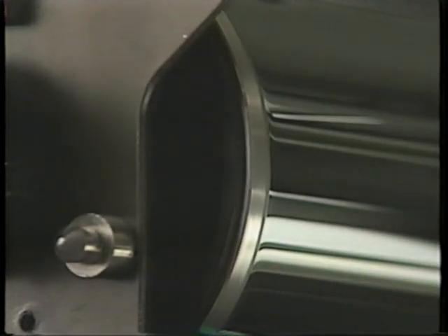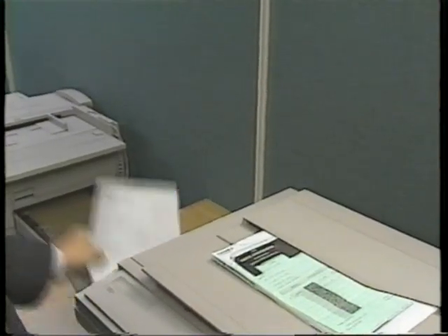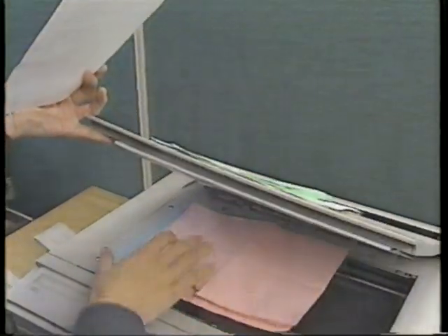When the sensor detects a dark original, lamp voltage is increased a certain amount to create a brighter reflection and a balanced latent image on the photoconductor. When the original is conventional white paper, no adjustment is needed. The normal lamp voltage allows the machine to produce a clean copy.